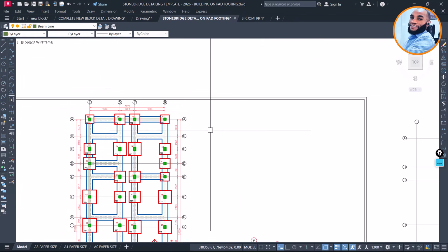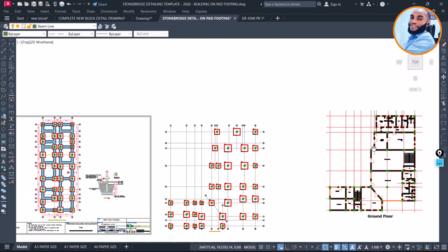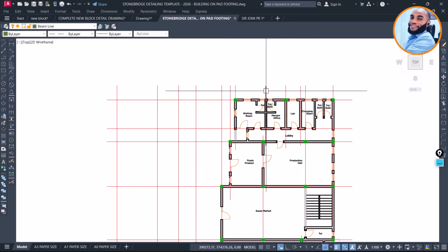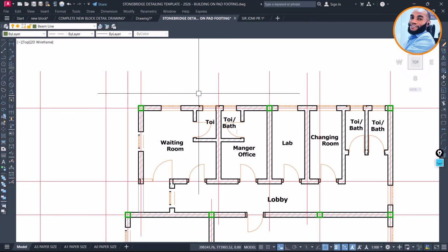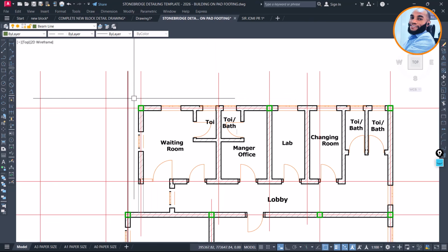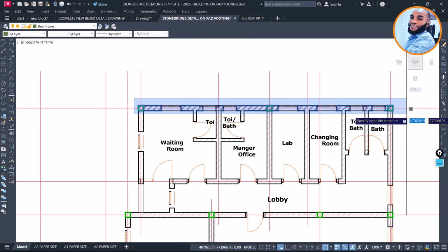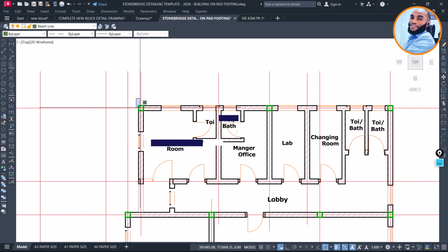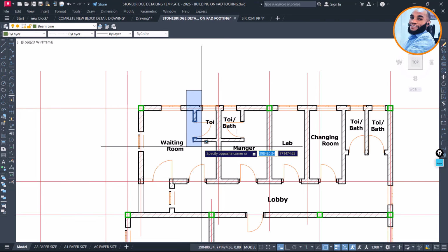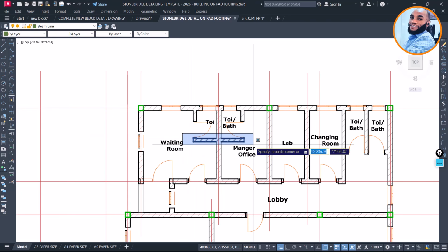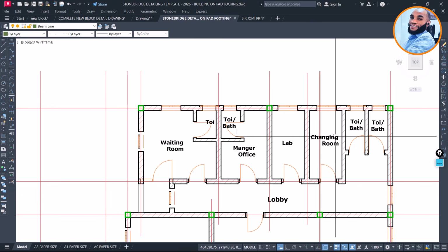That's fine. So I'll come now. I will not just go and copy all the wall lines that I'm seeing here and then replace that. I won't do that. What I will do, there's what they call major block walls. For example, these are major block walls of this building. This one also is a major block wall. But for toilet walls, these toilet walls can sit on the DPC. So there is no need for them to dig them. They can sit directly on the DPC floor.